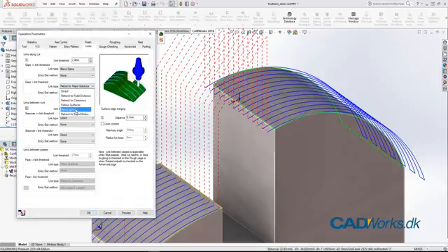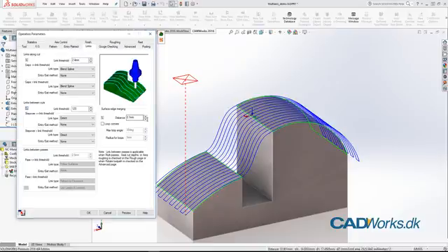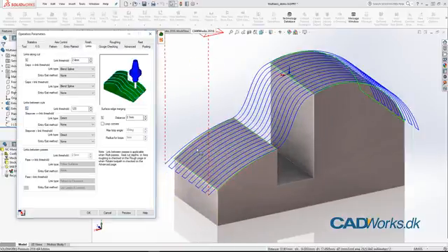But I'm going to use the blend spline option. The blend spline is going to follow the surface and just create a spline motion between the 2 points, the exit and the enter point. Now that looks really nice. I can run high speed milling, but there is this issue. I'm coming in with full feed motion, then stop and go full feed motion and stop, and then yeah, you get the picture.